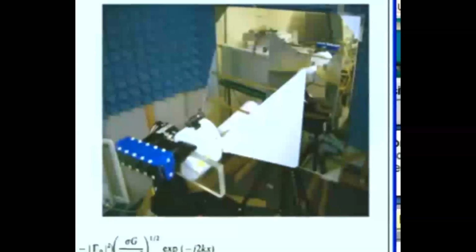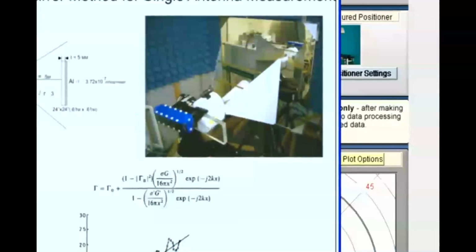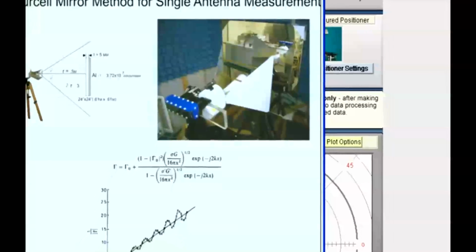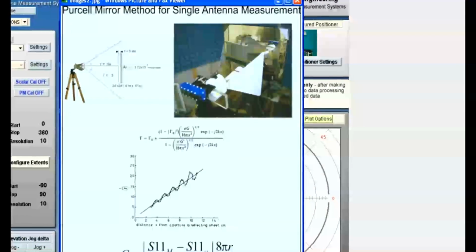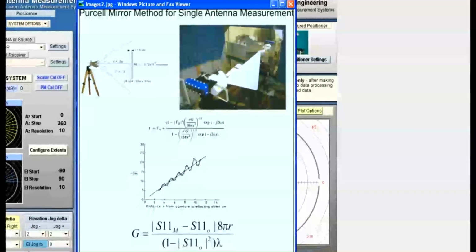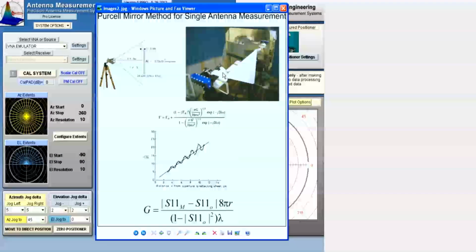That was an acceptable methodology unless the antenna itself experienced a finite mismatch. Later, it was modified to include mismatch. When looking directly into a mirror, the antenna under test sees its image at equal distance on the other side. The reflection of the antenna interacts as a mismatch so that the S11 can be seen to have a variation. This variation manifests itself as a variation in the true gain.